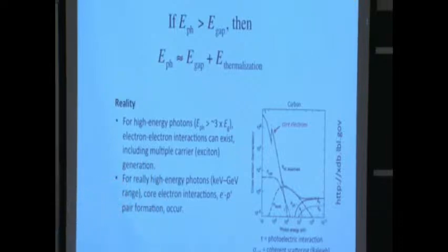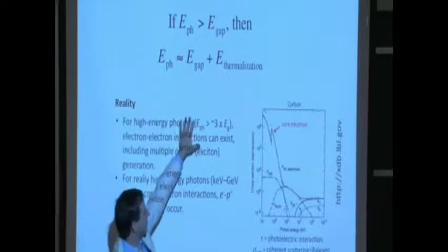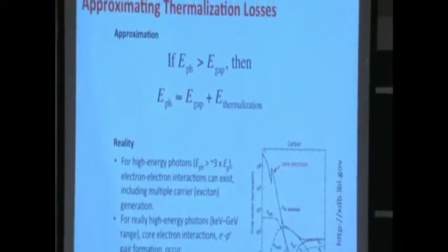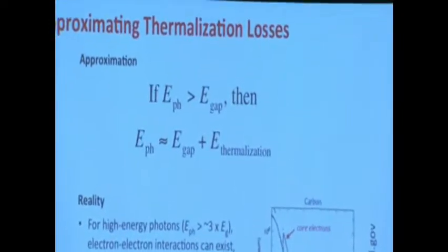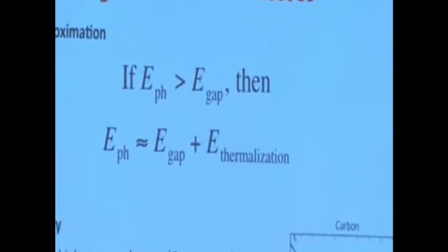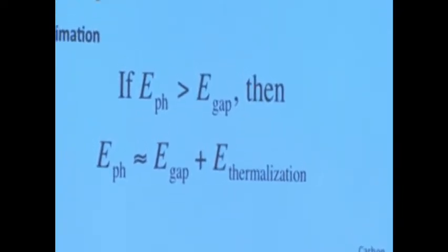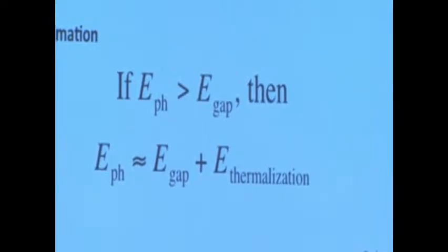So that's, I kind of wanted to hide all this down here. Forget this exists right now. Let's focus on that top part. So that's the easy way of thinking about it. We're going to be thinking about this in terms of just any photon coming into our device with a larger energy than the band gap is going to generate one electron hole pair and lose some energy due to thermalization.